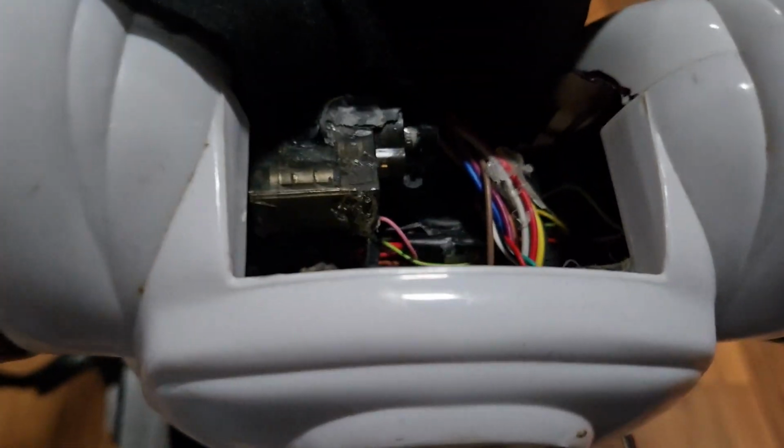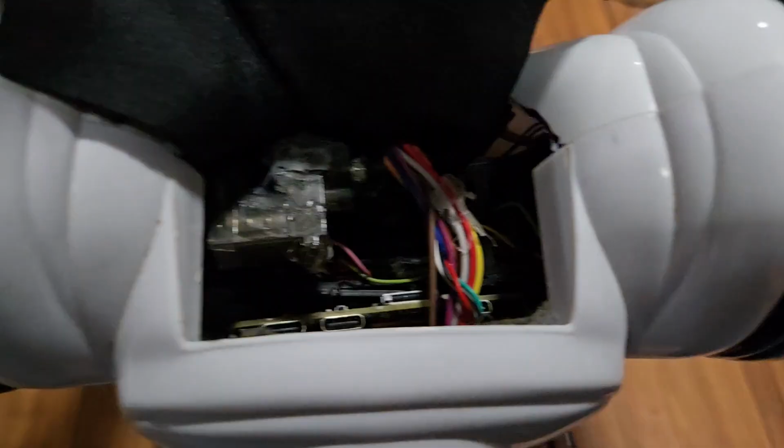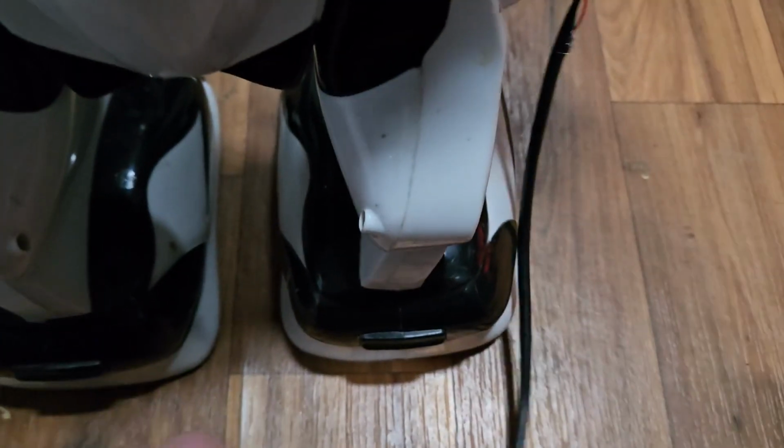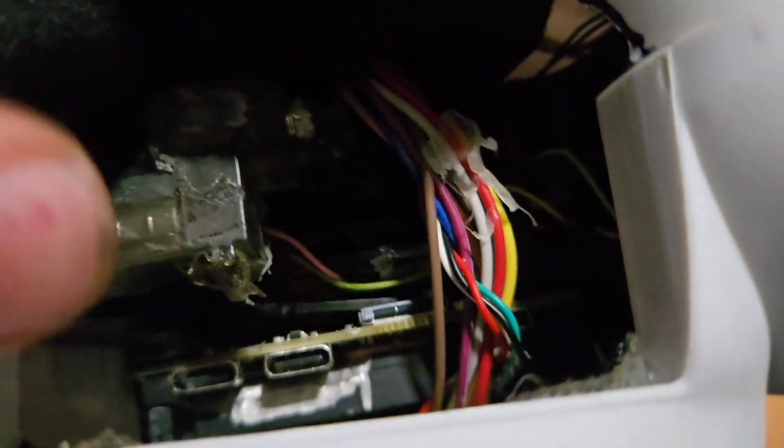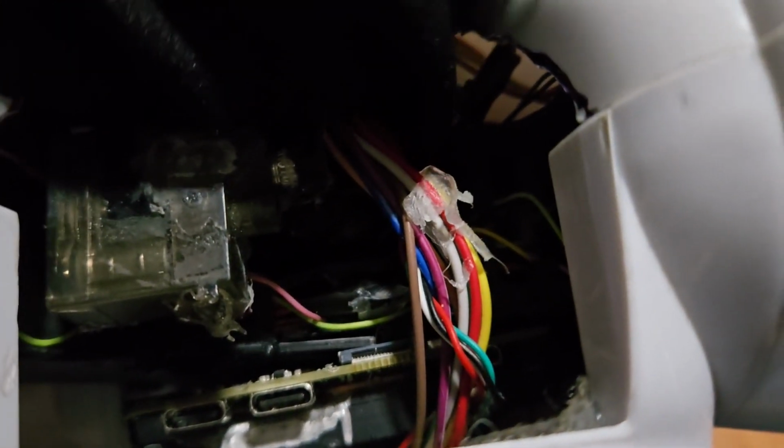Again, the project is good in theory, but there's no field testing, you know what I mean? So I don't have that adapter yet, but once I do have the adapter, this USB camera goes straight into the back of the robot and over the frame right by the side of the servo where there's nothing on this side, and there's all the SPI and I2C wires coming up from the main board. That's where you're going to run your USB connection through the frame and to the back and to this USB connector right here to avoid interference as much as possible.